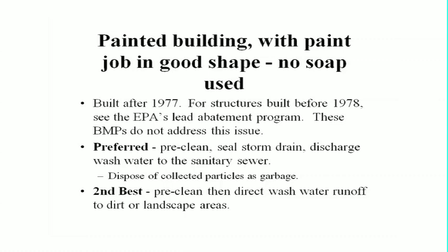The preferred method is pre-clean, seal the storm drains, and discharge the wastewater to the sanitary sewer, which is always going to be your first choice. Dispose of the collected particles as garbage. Second choice: pre-clean and direct the wastewater runoff to a dirt or landscaped area.